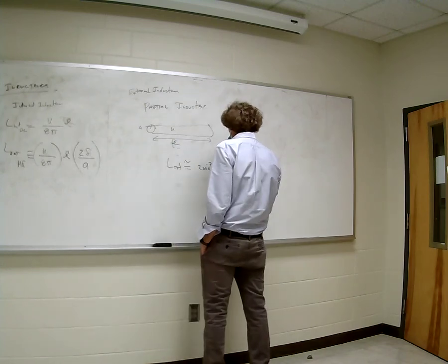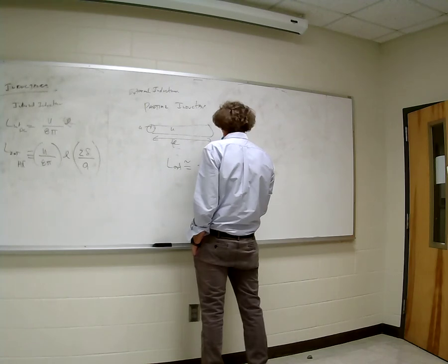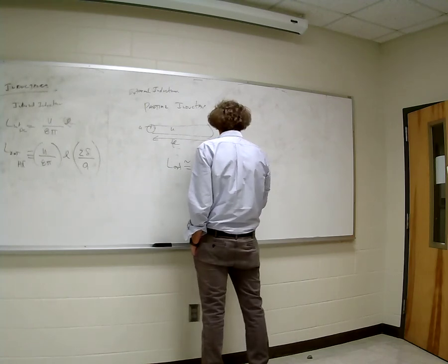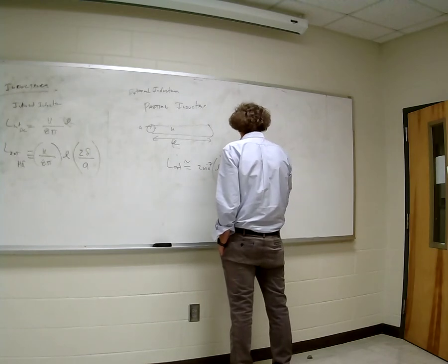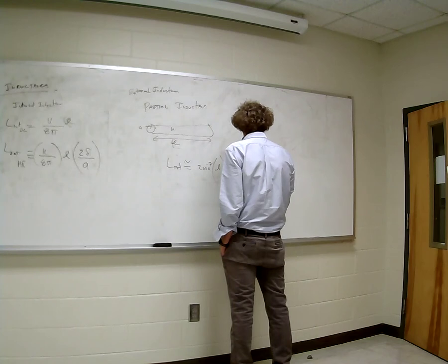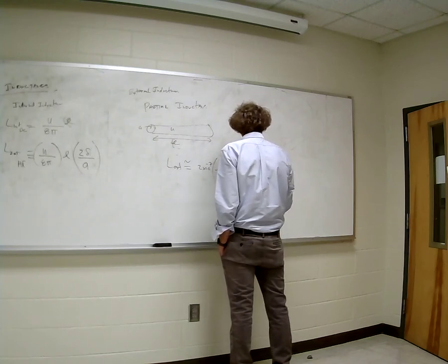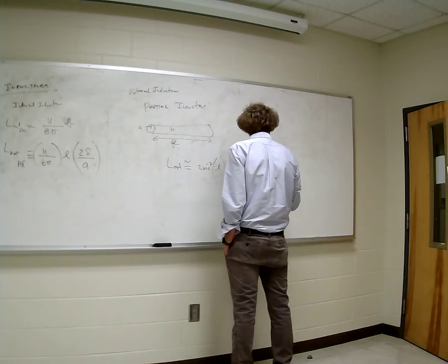And this is going to be henries per meter, but it'll end up being henries, times the length of the wire, and then it will be the natural log. You can look in his book. Natural log, and what they're going to have here is going to be proportional to L over 2A minus 1.